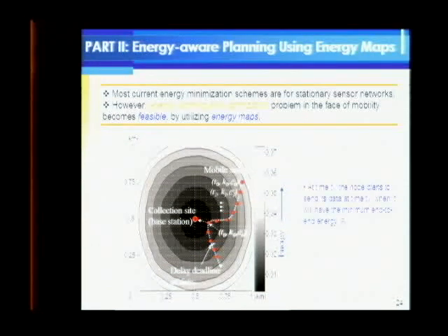Now, if you did not have an energy map, you would not know when to transmit. The current protocols, for example, just try to send right away. But that may not be the best thing. Given this kind of energy map, if this is my delay constraint here, then I can say, it looks like this is the best point to send to the collection site, and I will wait until I get to this point to send there. If you're using a bits per joule kind of metric. If you're interested in the average data rate, maximizing the average data rate to send that data, then you can do trajectory-based water filling. Along this trajectory, you can water fill your energy such that you send high data rates as you're approaching the collection site, and then low data rates when you're away from the collection site. Now, this is, of course, in your paper too.